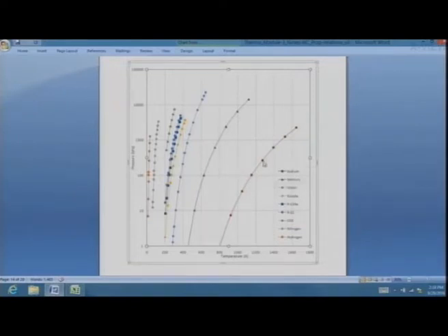But if the pressure is increased, it does the same thing. So all these substances are basically showing us the same thing: you increase the pressure, the saturation temperature increases, or vice versa, and this behavior ends at the critical point for all substances.